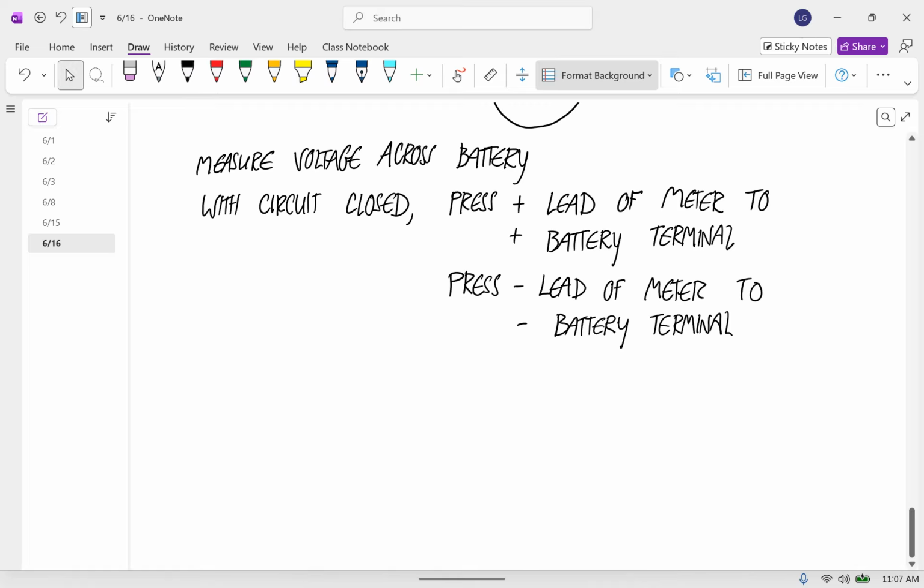Are you getting a value for that? This should all work, because with the voltage and resistance measurements, even if the fuse is blown, it still works. It's only the current that gets affected when the fuse is blown.